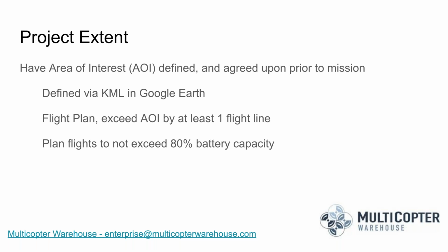And one thing just for safety I want to point out is it's always good to try to plan your flights not to exceed what I'll call 80% of your battery capacity. I've found that if you push your LiPo batteries beyond the 20% threshold, or landing once your battery is at or below 20%, that will have an impact on the longevity or the number of charges you'll get on that battery. So try to always plan your missions to maybe throw a battery warning at about 30% and try to be landed by the time you get to 20.